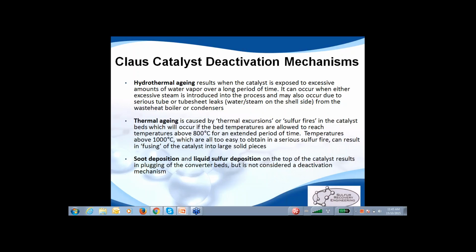If we are too deficient on our fuel gas sweep or burn, we will generate soot that will form typically on the top of our first converter bed. Thus, a lot of our work is centered around general performance evaluations of SRUs. However, we do support many of our clients going into formal shutdowns or turnarounds by ensuring that we have a properly carried out SRU shutdown and or startup.